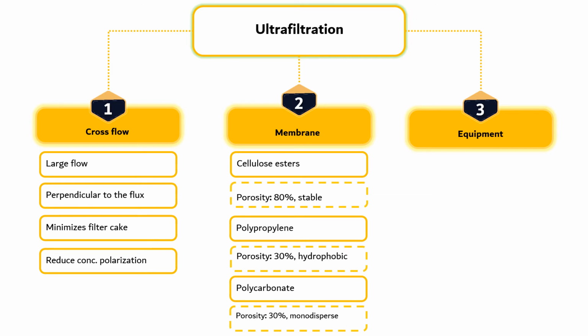The third key characteristic of ultrafiltration is the membrane geometry in the actual equipment. There are four common membrane geometries. The first type is flat sheet. It has a membrane area up to 1500 m². It can be disassembled for cleaning and for replacement of defective membranes. It has the smallest area per volume of the common types, so tends to give low ultrafiltration fluxes per volume.